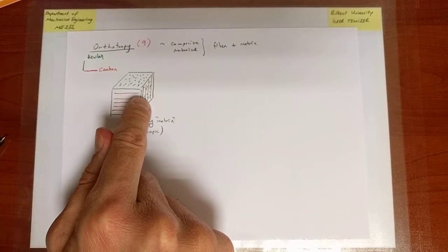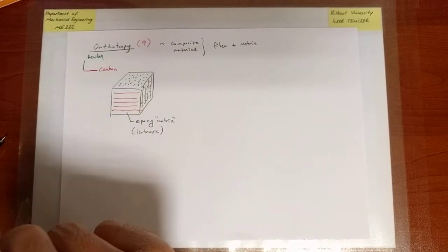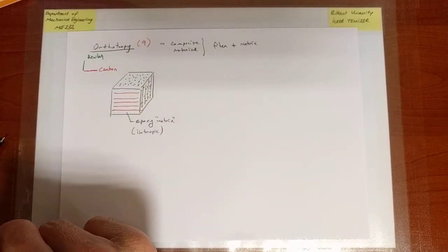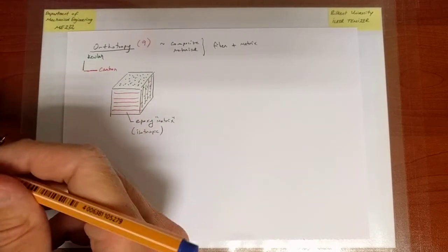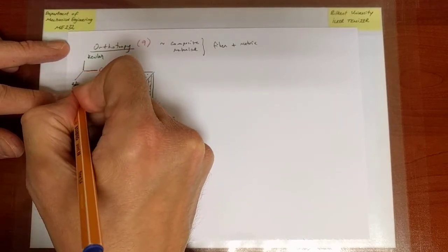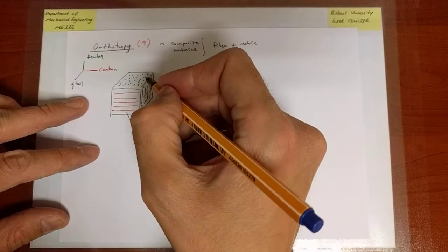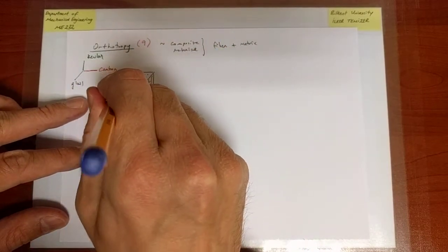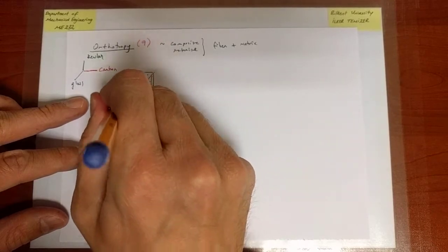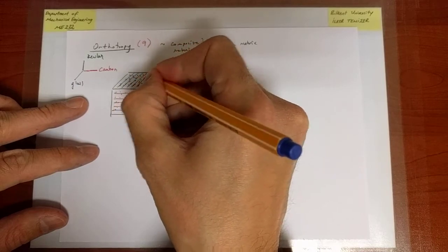But once you put it into something, then together with the epoxy matrix, it can also possibly carry some compressive load. And finally, you can have fibers running in the other direction, and let's call those glass fibers. They've been employed for a long time, so we are going to stick them along the remaining axis, and they are going to run in that direction.